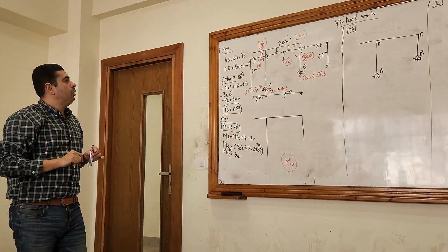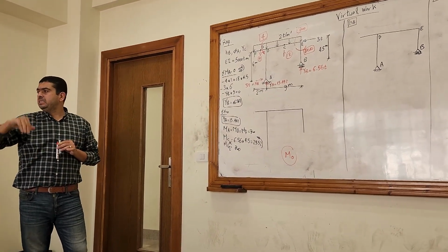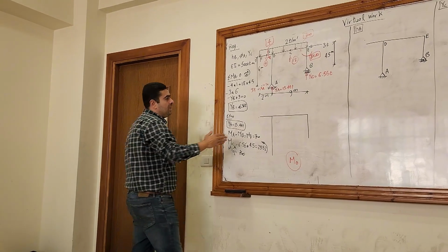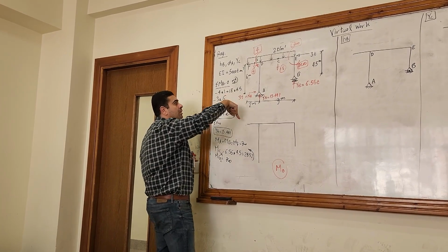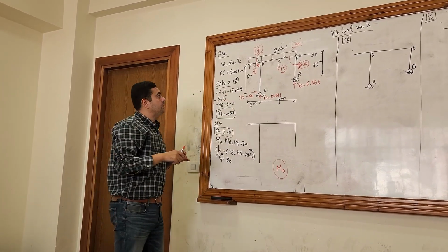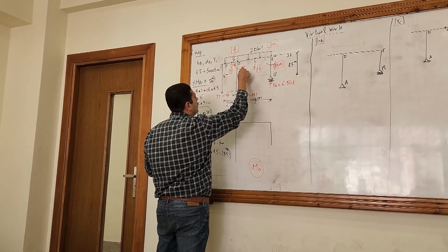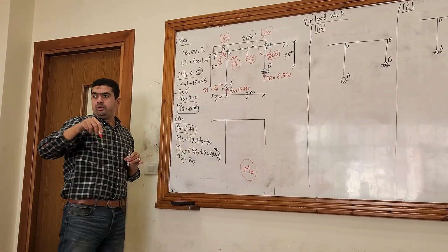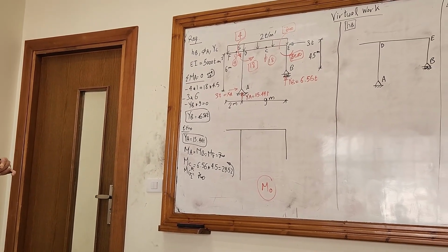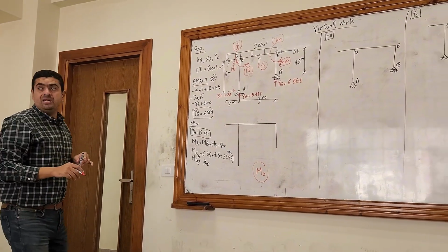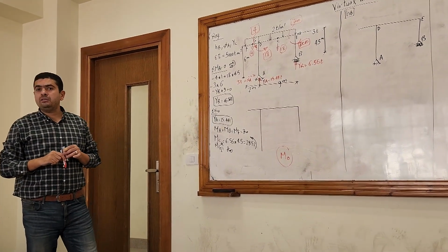Okay? What about the moment at D, but from the part DA? The YA will not have any moment. Only the 3 multiplied by 6, which is 18. Look at the direction. It's like this. I put it on the member DA on the direction of 3 times 6. So now easily I can calculate the moment from the third side.